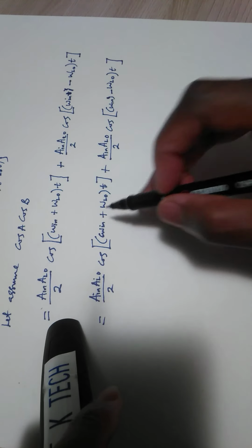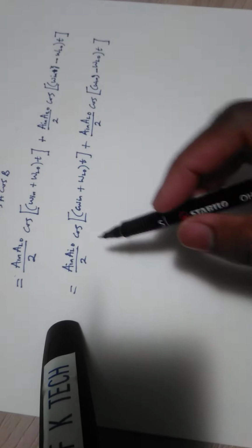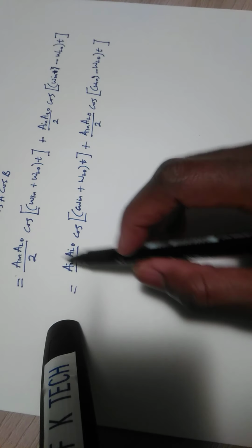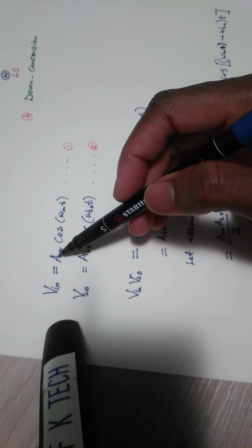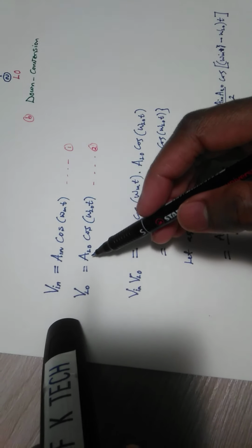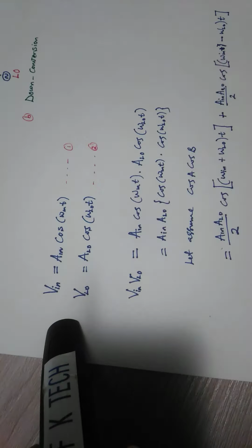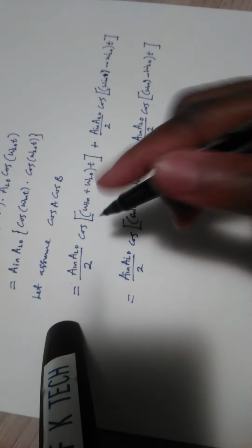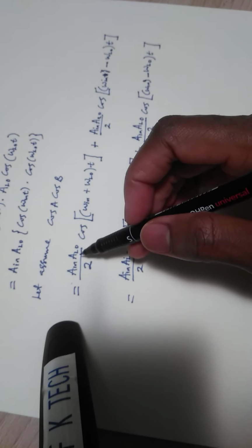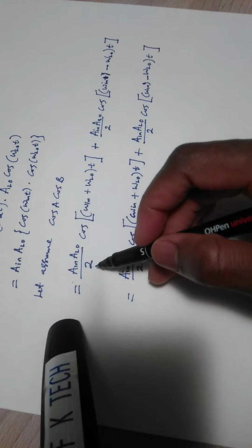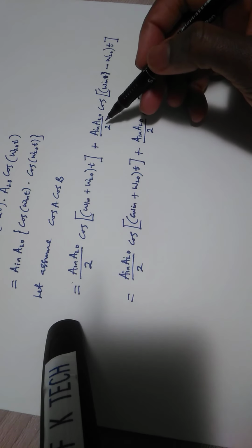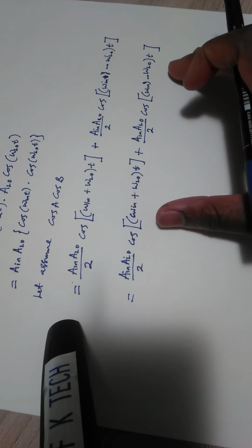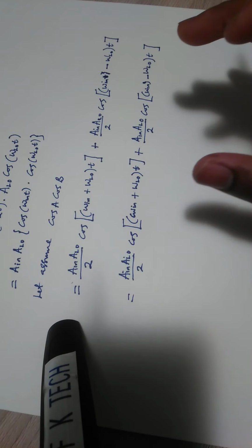And what we mean by nonlinear amplification is that you can see the amplitude of the IN signal and the amplitude of the local oscillator signal are multiplied together, because you don't say you add them. So logically it's multiplied together and then halved by the cosine formula, and the same thing for the other part. So we have two separate parts.